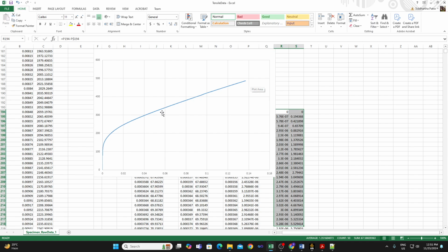Okay, for example, it is changing from 300 to 500 in a span of, let's say, 10% strain, so 0.04 to 0.14. Remember, this is true plastic strain, so it is much less compared to 0.15 from where we removed the extensometer. So since 200 megapascal is changing over 0.1 strain, that is 10% strain, the slope over here is around 2000 megapascal. So that's what we are estimating. Okay, so we'll keep that estimation in mind. So one of the Chaboche terms will have a Ci value of 2000 and a gamma I value equal to 0.